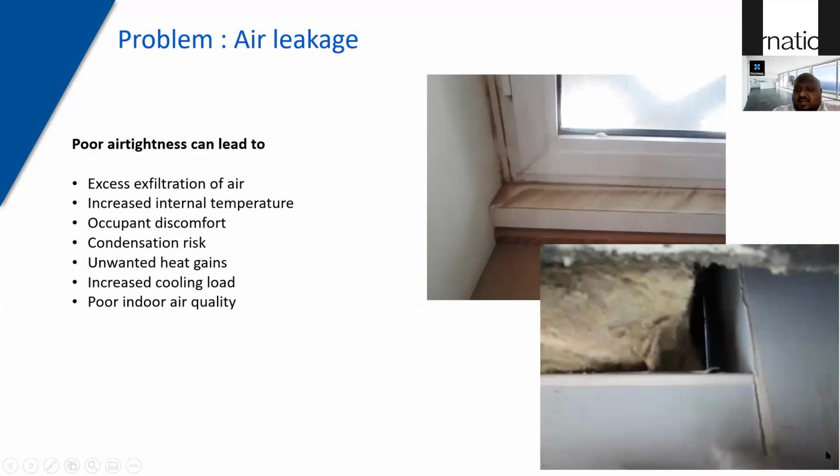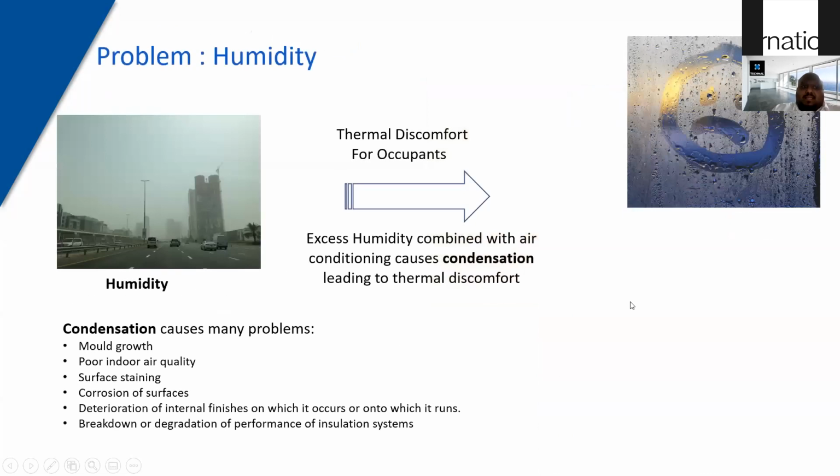So this is essentially an image of a mullion and transom on the spandrel, and what could essentially happen if a non-tested curtain wall is used. You have exposure to outside air to come inside quite easily, and quite disturbing and leading to all these issues which I just mentioned. So the humidity issue is again part of a non-tested window, door, or curtain wall.